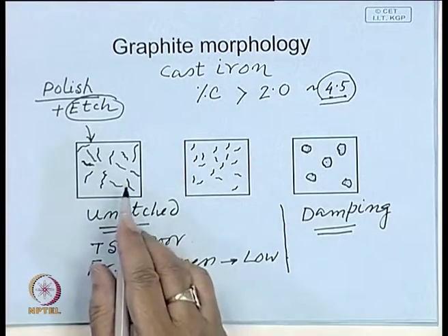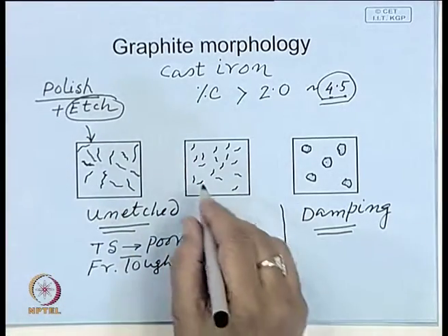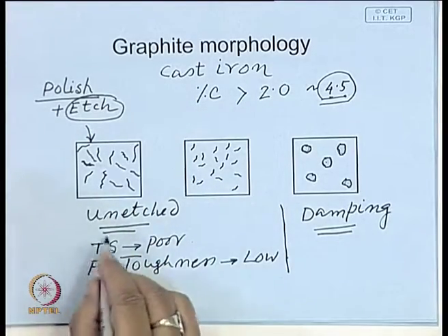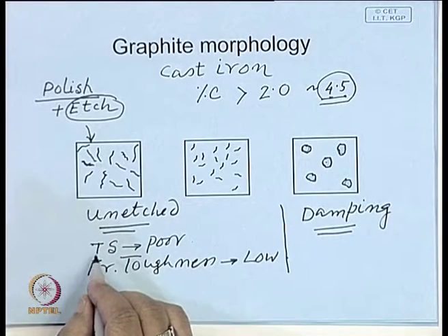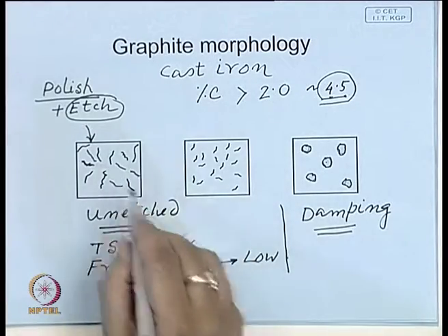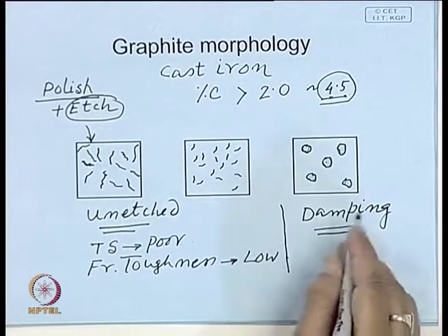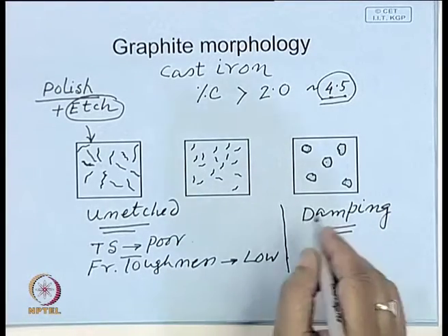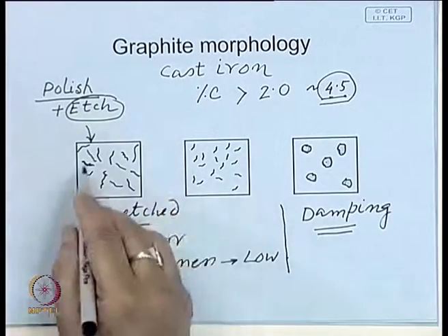So, therefore, it is a very commonly used material for construction where that material is not subjected to tensile stress, but compressive stress. It has good compressive strength, no doubt, and you need damping resistance. Say, suppose the turbine bases, where the turbine is supported, or machine bases, they are made up of this type of grey cast iron.